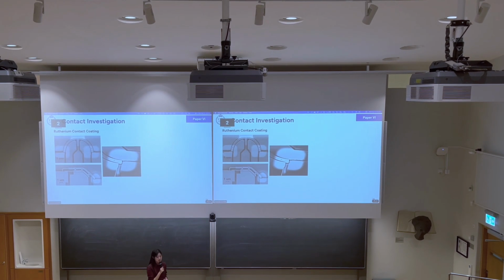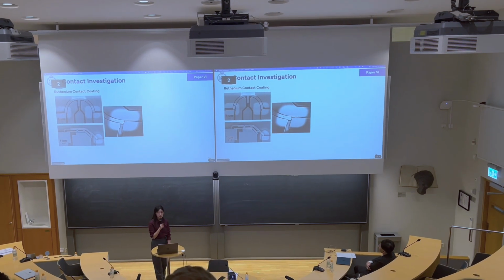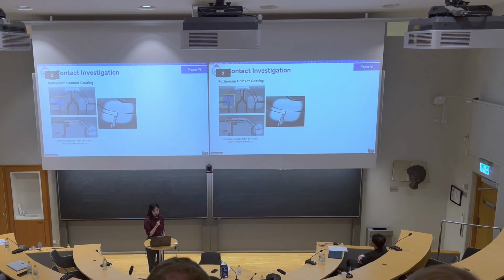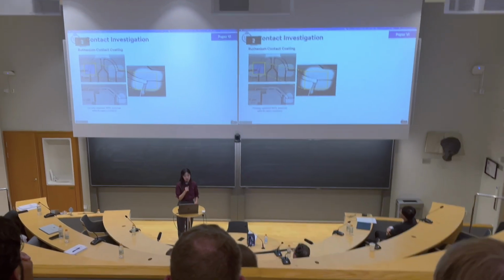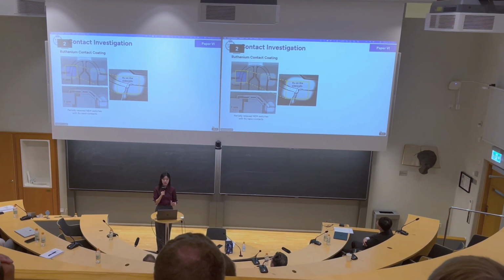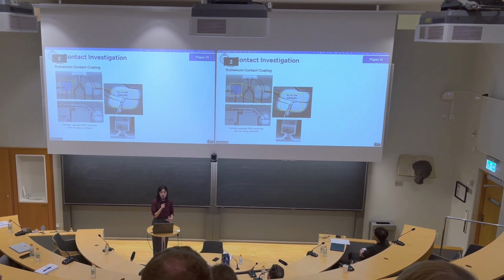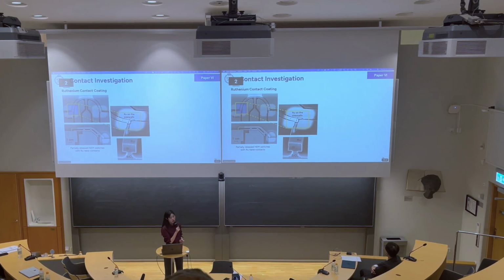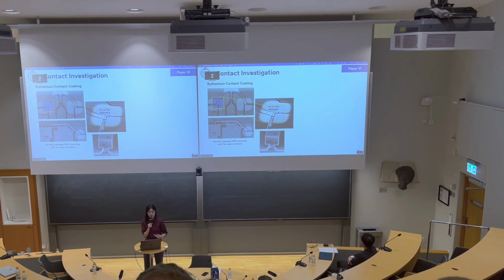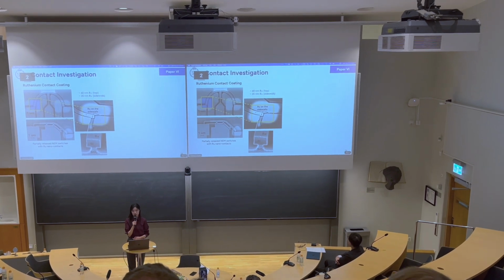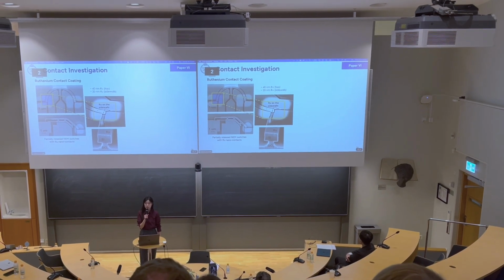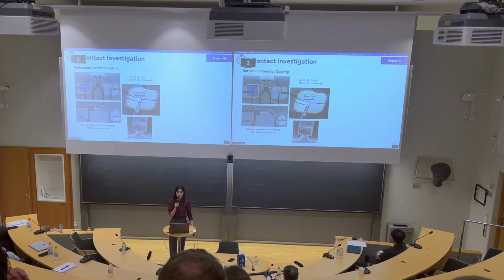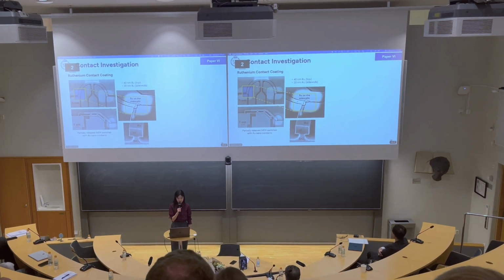So on this image, you can see that we also deposited the ruthenium contact through the window lift-off method with sputtering. And we know that it's an in-plane moving NEM switch, so the sidewall coverage will be very important. So we made a cross-section on the switch contact, and you can see there is very nice sidewall coverage for ruthenium on the switch tip. And we know that if we deposit around 40 nanometers of ruthenium on the top layer, then we get around 50%, roughly 20 nanometers, on the sidewalls.